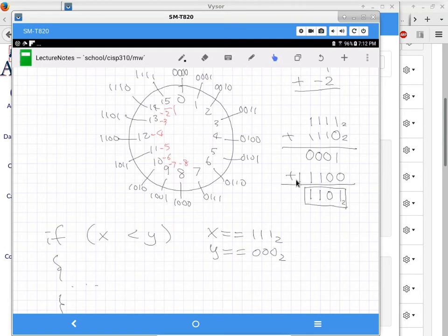So when you have a carry and it's signed, unsigned, is it considered overflow, or we won't talk about it? That's a good question. So after an addition, if you already know that you're dealing with unsigned values, if you set the carry flag, it means you have overflown what your number can represent. The result of the addition is more than what your bit numbers can deal with.